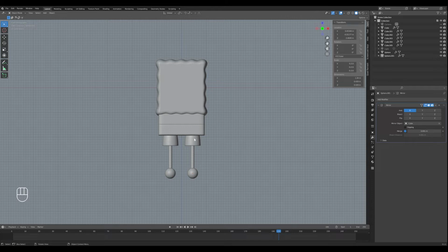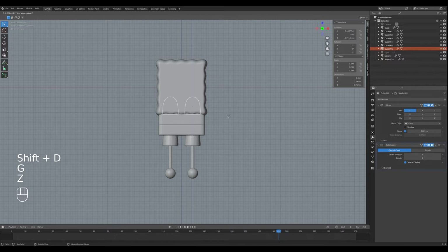So his sleeves are like a smaller version of the legs of his shorts. So we're going to click on these, duplicate, Shift-C, take them up, and move along the x-axis, rotate along the y, 90. So Control-Z, wrong way. So rotate along the y, negative 90 degrees. And there we have it. We need to make these smaller though. These are not that big, so scale down. Let's try that. Move them up.